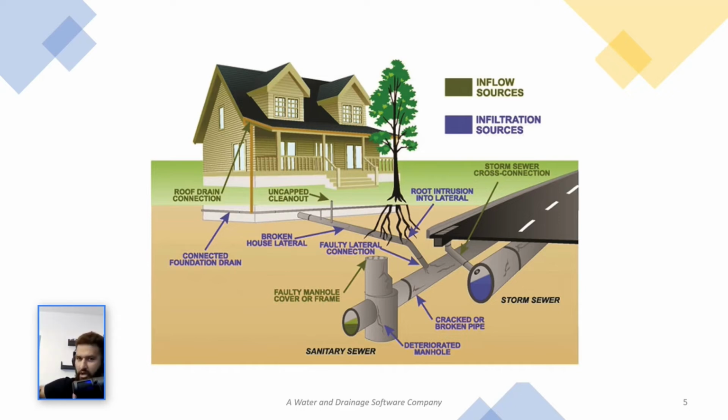If there is a fracture on that pipe, because we're having flow inside of the sanitary sewer from our residential area, we're actually generating a negative pressure. And the negative pressure in the physical world means that we're going to have suction from inside of the pipe.